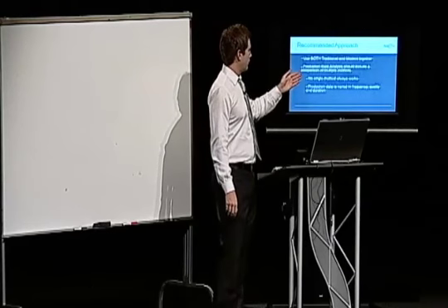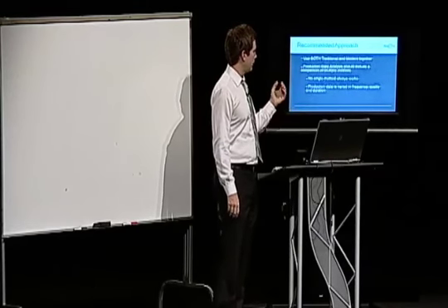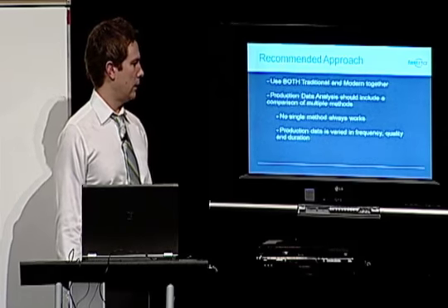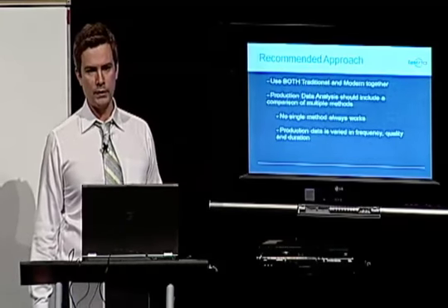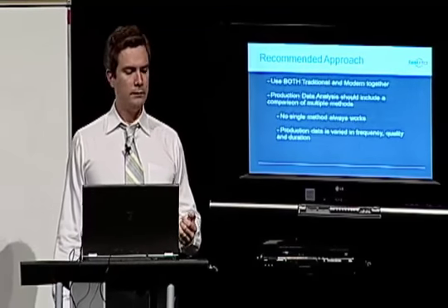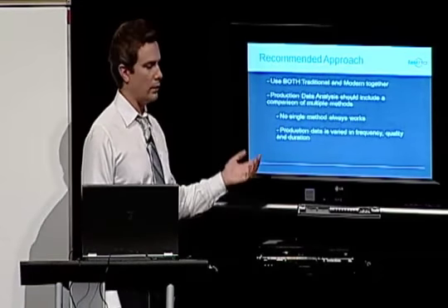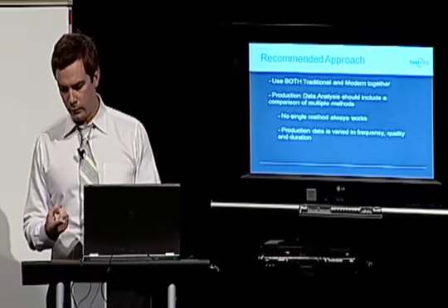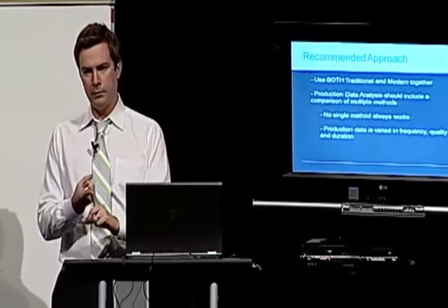Production data analysis should include a comparison of multiple methods. There is no single method that's always going to work 100% of the time. Production data is varied in frequency, quality, duration. These are things that we all know. You want to be able to analyze public data that comes in monthly volumes. Maybe you don't have any flowing pressures available for those. You also want to be able to analyze minute by minute SCADA data, high frequency, high resolution rates and flowing pressures. These are all different types of data, and we need an approach or a series of different methods that can handle all of these different sorts of data.